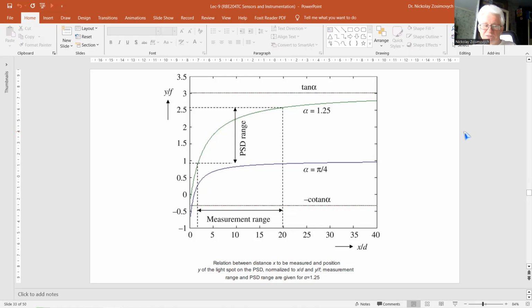The size of the light spot image on the sensor depends on the beam diameter and divergence, and may be substantially larger than the required resolution of the sensor. For a PSD, this is not very relevant because it responds to the optical center of intensity, which lies on the main axis of the light beam. And obviously, the spot size should not exceed the width of the PSD.